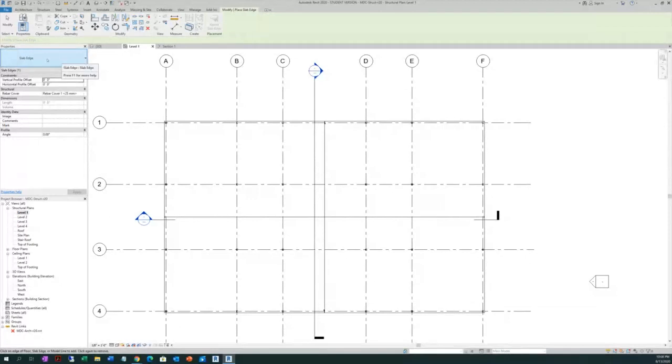I want you to make sure that you know this. A profile is a 2D, in this case for Revit. A profile also when you do your mullions is a profile. A profile also when you're doing some molding, or what we did last night, that reveal or carpet way, is a profile. It's a 2D that you load here, okay? So in this case, the slab edge. You go to the edit type.